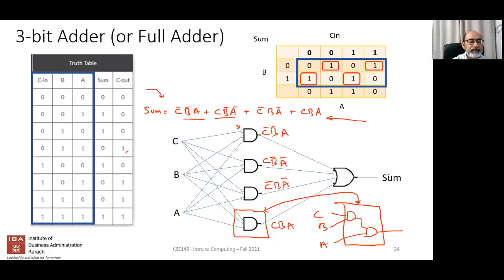Similarly, this 4-input OR gate can be thought of as 1, 2, and I think you'll probably need 3 OR gates. 1, 2 feeding in over here, the third coming in here, the fourth coming in here, and so 3 OR gates together form this 4-input OR gate.